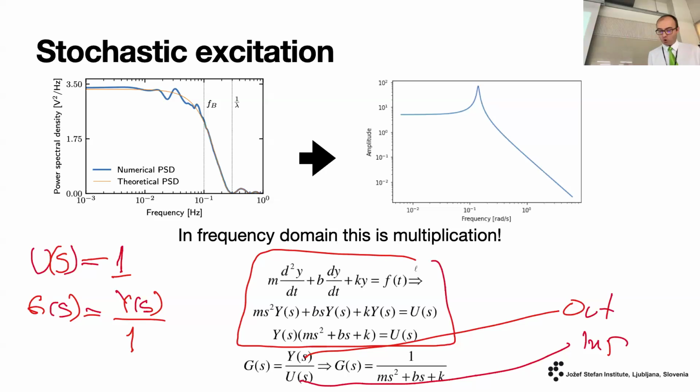Only one signal. So all we have to do is find a signal that has a Laplace transform constant to 1. And we know it's called white noise. Or actually, in this case, it's a Dirac signal. It requires infinitely high amplitude. It's really hard to do. But what we can do actually is generate a noise-like signal that has a flat spectrum.